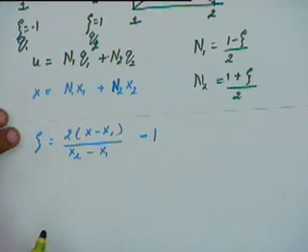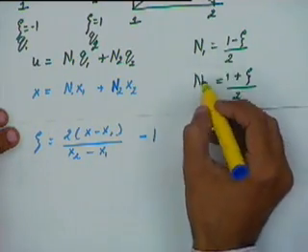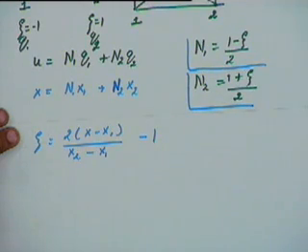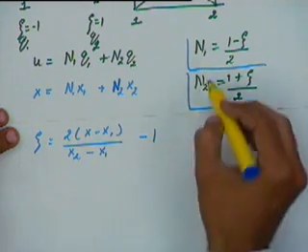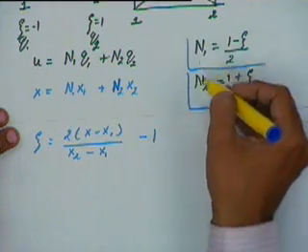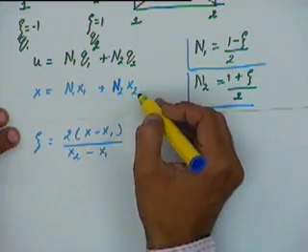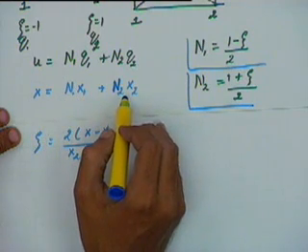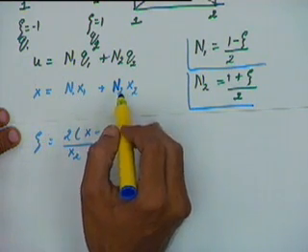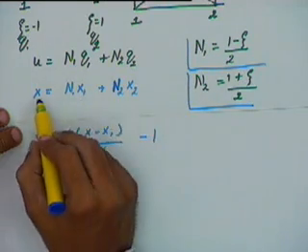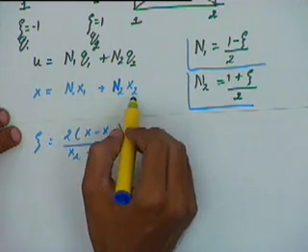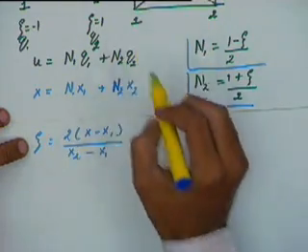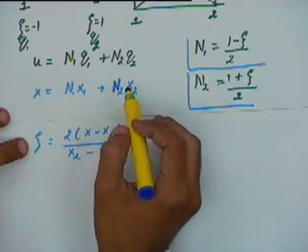Okay, this is how we have defined zeta, and n1 and n2 have been defined like this. If I put the value of n1, n2 and zeta back into this equation, you can verify that x will be equal to n1 x1 plus n2 x2. Okay, and that should be clear otherwise also, because x is a linear combination of x1 and x2. We have defined zeta to vary linearly between node 1 and node 2.